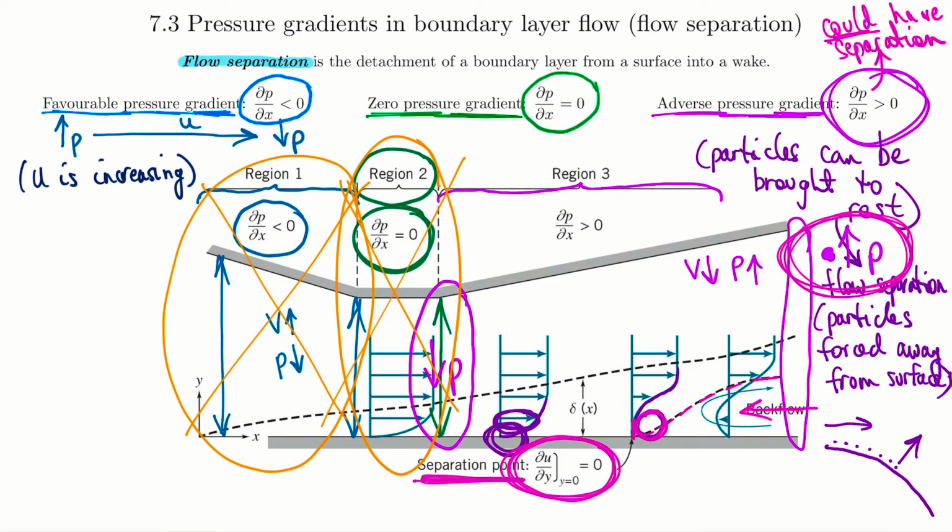We saw some examples of adverse pressure gradients and what they can do to the flow between parallel plates. So we know that the pressure is going to start to push the flow backwards, so you're going to get this backflow right in this region, where the flow is going this way, and this flow is going this way. The only way you can have mass conserved when these flows are coming towards each other is for that flow to go away from the surface.